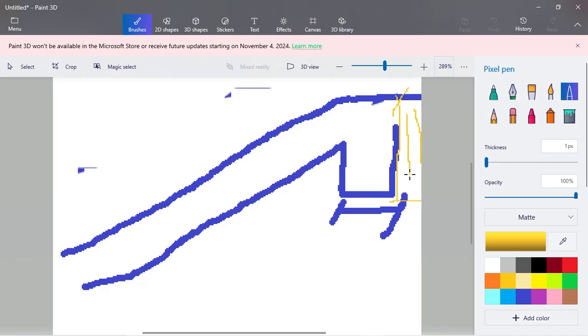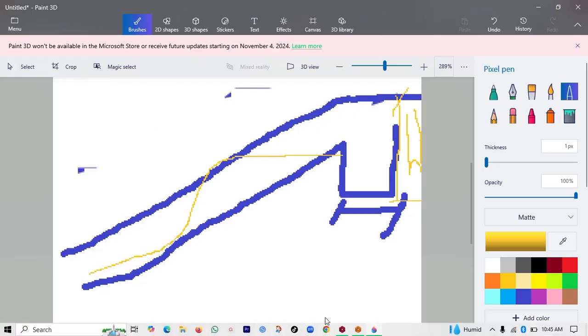Yeah, their meaning. So these ones enable us maybe to check for deflections, to also provide for the reinforcement in this stair slab. As I told you in the beginning, stairs are designed as slabs, and also one-way spanning slabs. They don't have the reinforcement in both the x and y directions. They only have in one direction.